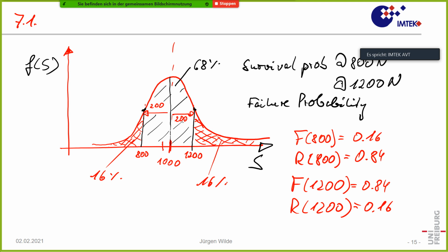So it's just the probability of survival in case we have a certain load and a distribution of strengths. Of course, you can also treat it the other way around. You could say you have just a certain strength, which would be a unique value, so let's say a Weibull distribution with an extremely high exponent, that would be a function which goes up very high.